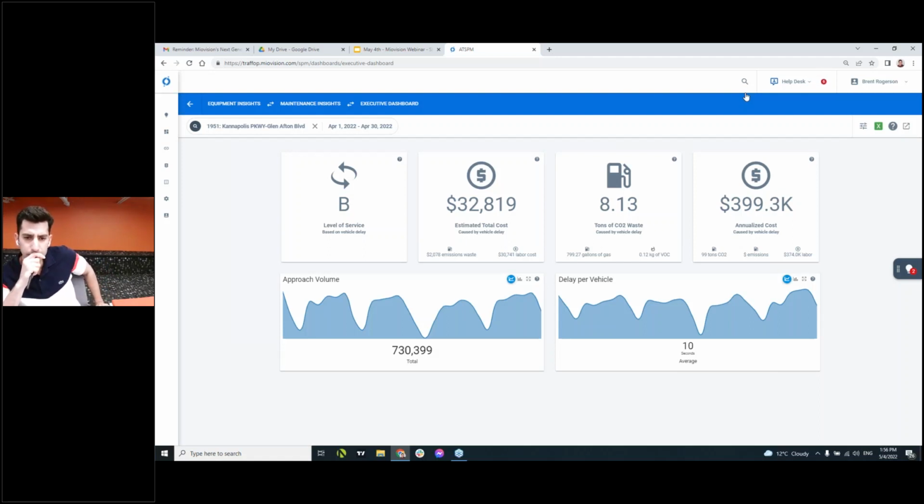I'll try, hopefully I answer what you're trying to ask here. Many of the ATMS systems leverage, this is probably the wrong word for it, a smaller or lower resolution of data. So the NTCIP streams from the traffic controllers, which provide about 30 or so events from the traffic controller itself, or even just the SDLC stream from the detection products, that really just gives you a small subset of signal status, pedestrian signal status, and detector status.